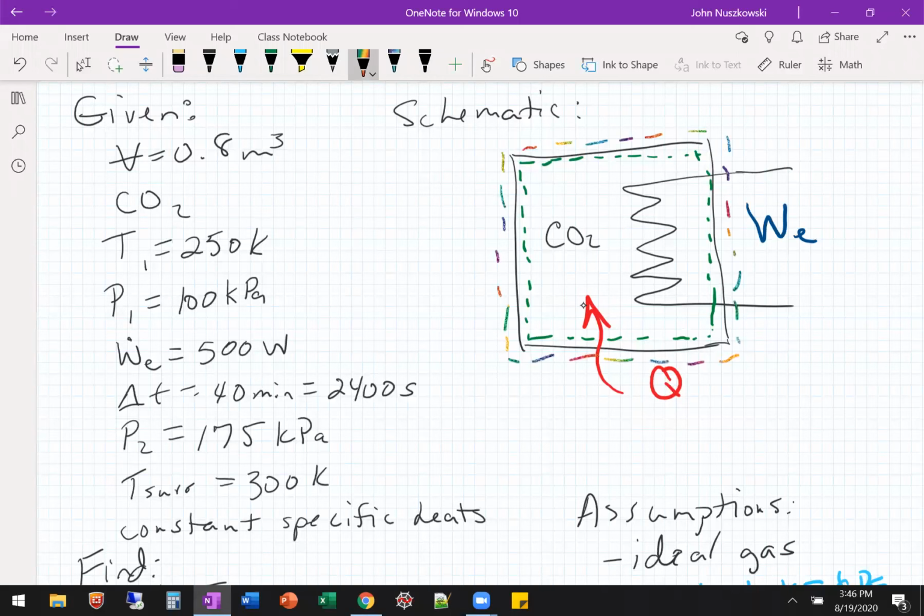Okay, so instead of it being where that green line is, it's where that rainbow line is right there, and that's T of the surroundings, right? This would have been what we don't know because it changes as heat is being transferred. It goes from T1 to T2, so it's not a nice set temperature if it's crossing the boundary right there. So we extend our boundary a little bit, okay? Because nothing's really going on with that air outside. There's no change. We can say it's staying steady, or it's very minimal. So we have this T surroundings then, okay?